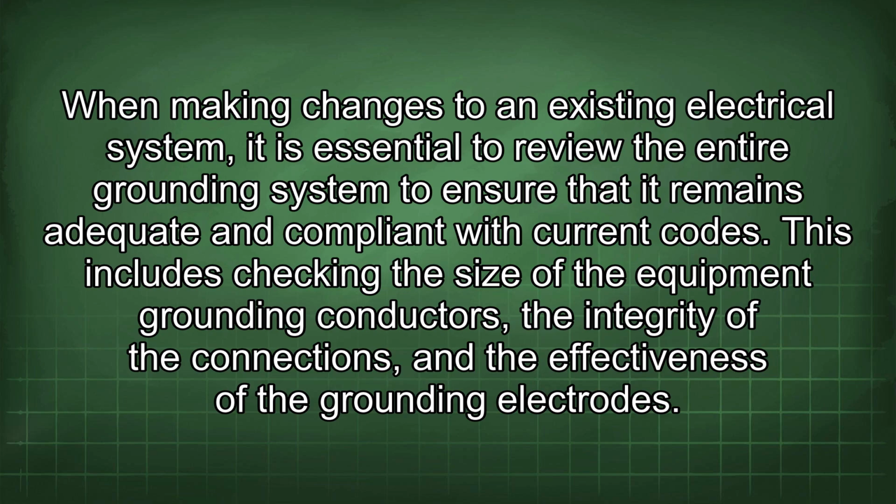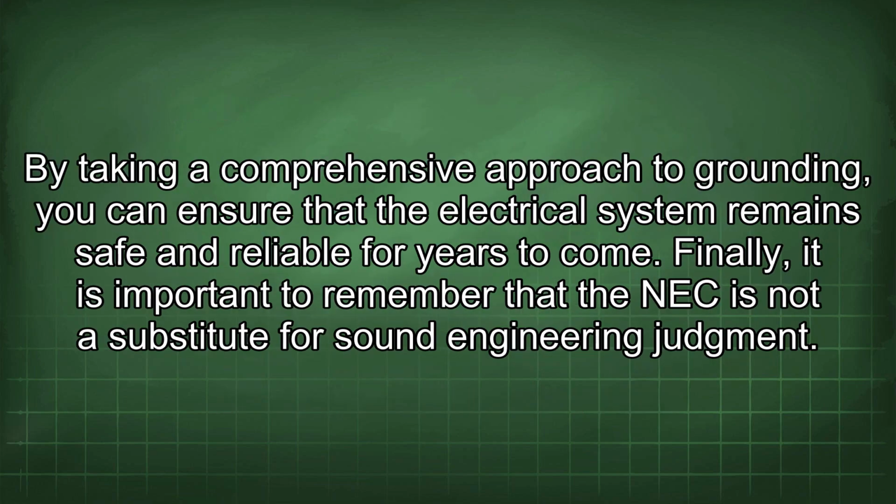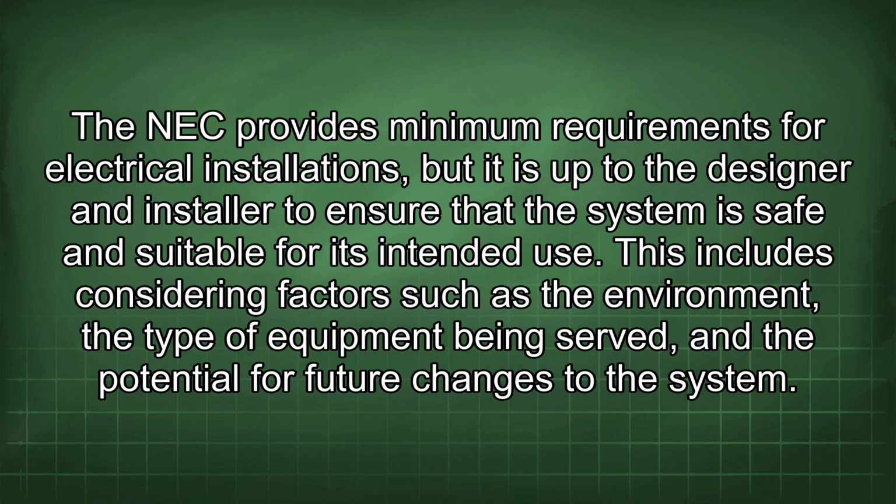This includes checking the size of the equipment grounding conductors, the integrity of the connections, and the effectiveness of the grounding electrodes. By taking a comprehensive approach to grounding, you can ensure that the electrical system remains safe and reliable for years to come. Finally, it is important to remember that the NEC is not a substitute for sound engineering judgment. The NEC provides minimum requirements for electrical installations, but it is up to the designer and installer to ensure that the system is safe and suitable for its intended use.